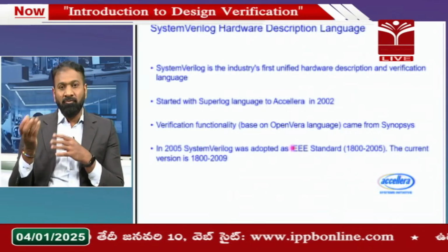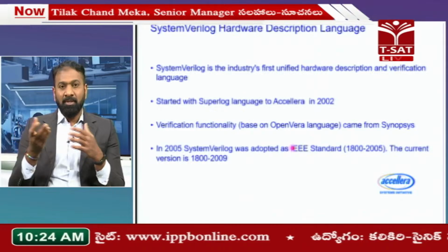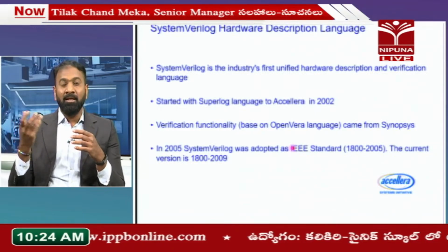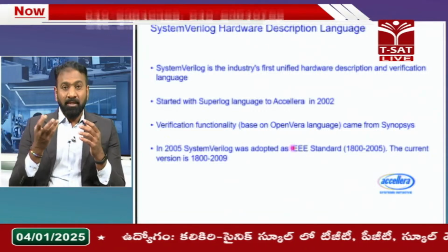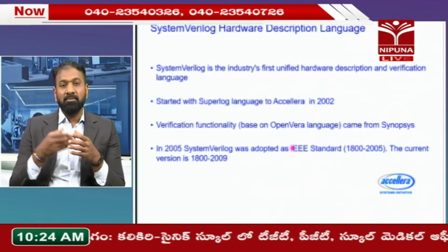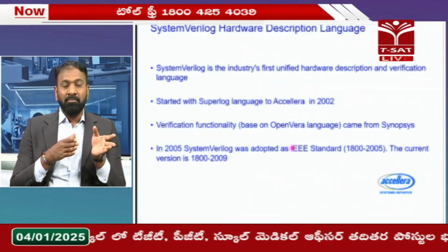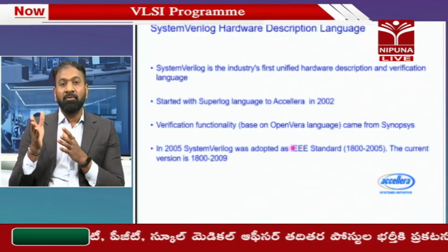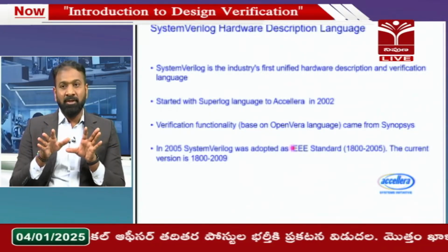If you have any software background, there is a difference between C and C++. The difference is the OOPS concepts and the high level abstractions which you can achieve with C++. A similar feature has been introduced by SystemVerilog. SystemVerilog is a hardware descriptive language as well as a hardware verification language. So, you can use it for creating designs as well as verification.